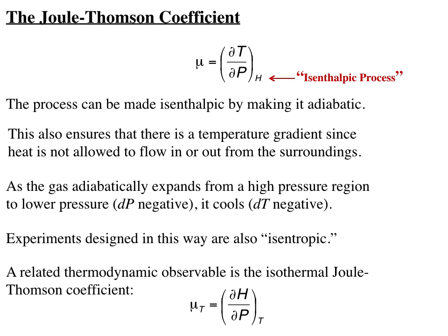And again, I argued this in our last lecture, that maybe you've seen something like that occur on the regulator of an LP liquid propane tank when you cook crawfish or something and the thing starts getting low on gas. You quite frequently see the regulator starting to ice up because there's such a dramatic cooling as the liquid expands coming out of the nozzle and into the burner. You can put your hand on that regulator and feel how cold it is getting. Even if there isn't ice on it, try that out sometime when you're hanging out.